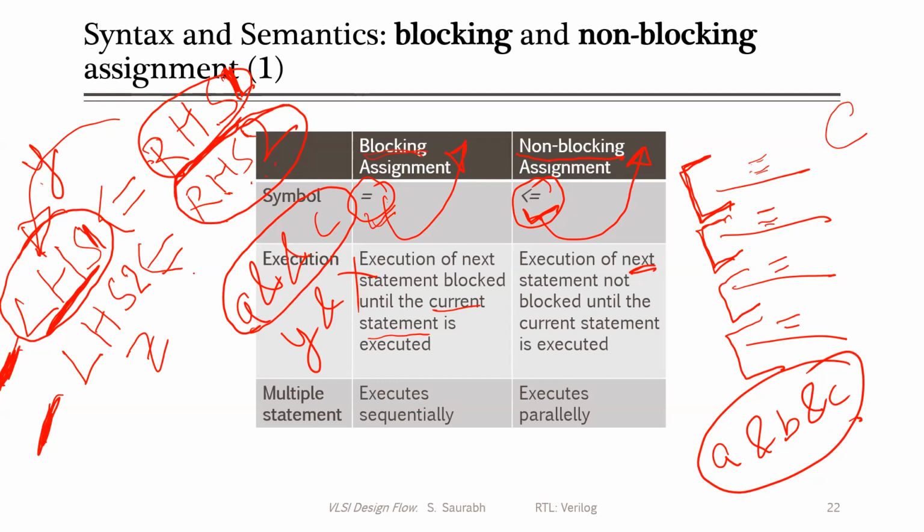Whatever the current value of Y was is assigned to the second RHS and kept. After the update phase, Y will change, but the second RHS will not change, even though it depends on Y. That is why the non-blocking assignment is different from the blocking assignment.